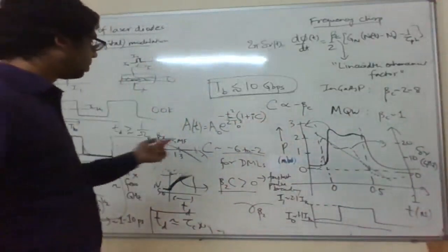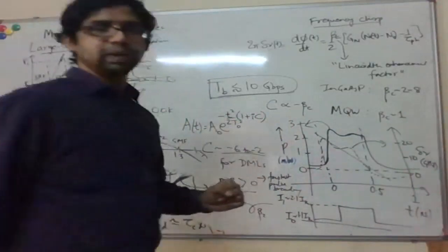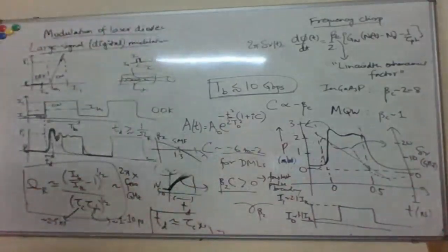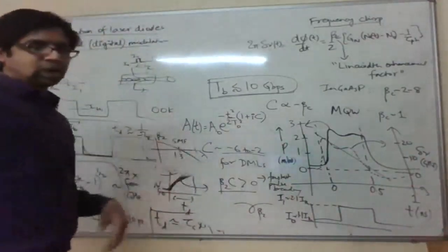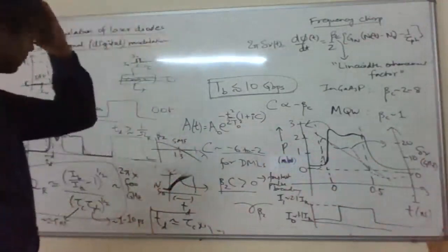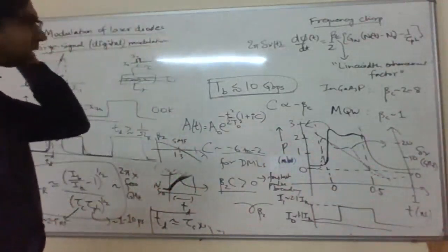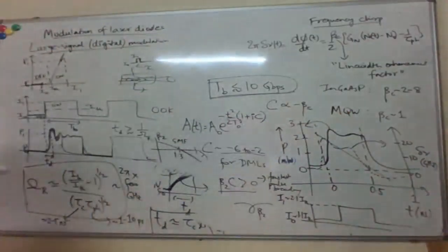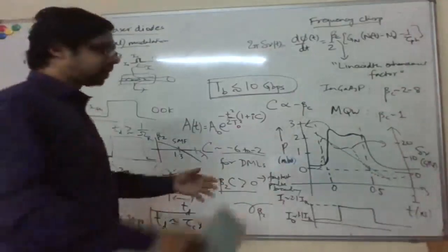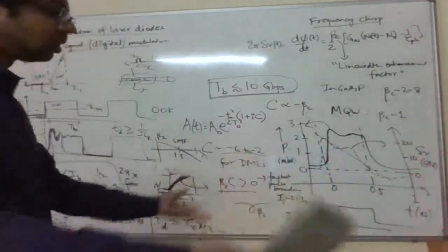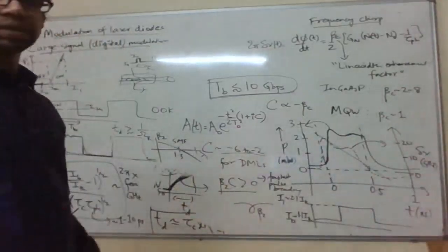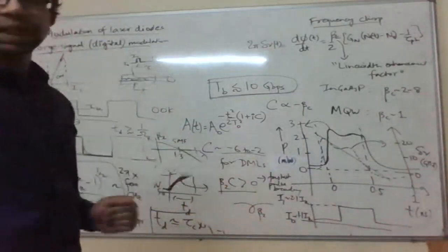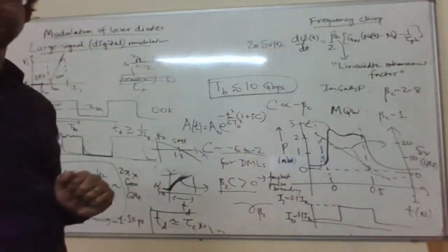But it's also worse than that because the dispersive effects will be even worse. So for these reasons, for high data rate long haul links, nowadays we typically use external modulation exclusively. But depending on the data rates you're operating, and maybe for local area networks, directly modulated lasers are still useful.